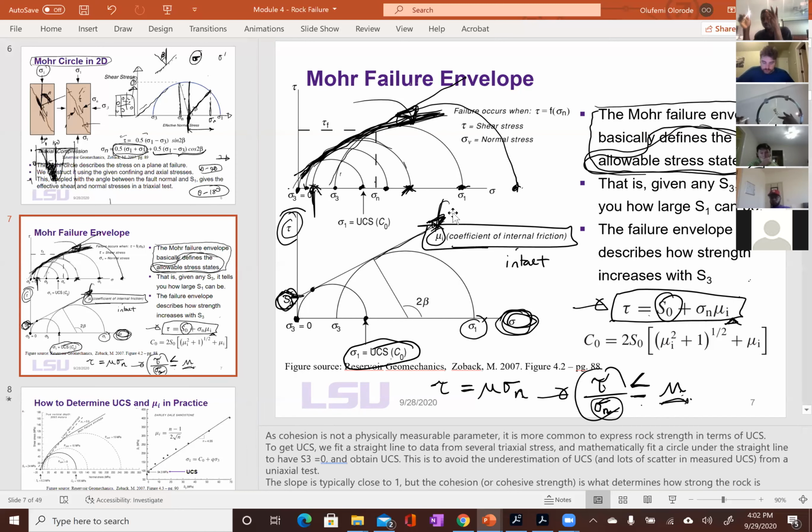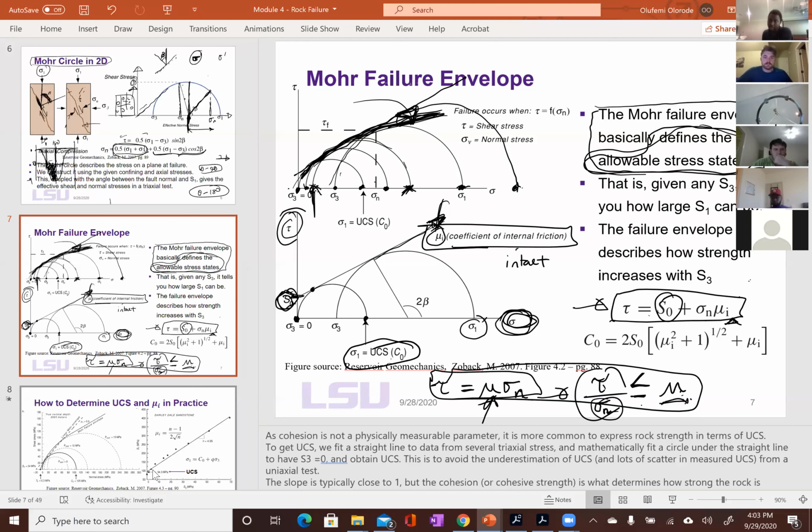And now you know there are three strengths of the rock, right? The compressive rock strength, the tensile rock strength, and the frictional strength of the rock. The frictional strength, that's like basic physics, right? There's nothing crazy there. We'll talk about that when we get there. But basically, this equation is all we're caring about. This is the frictional coefficient of sliding on that surface. And all you need is the shear stress on that surface and the effective normal stress on that surface.